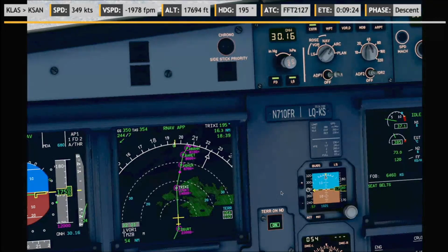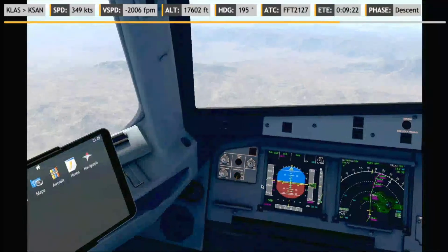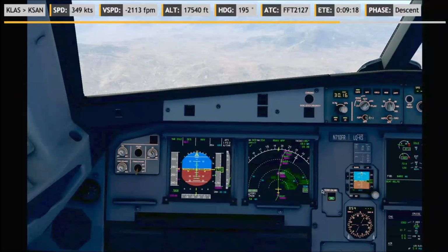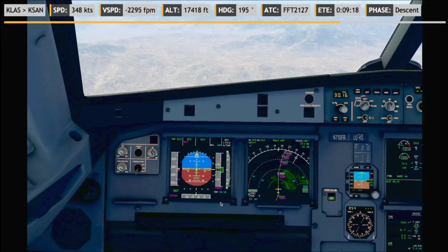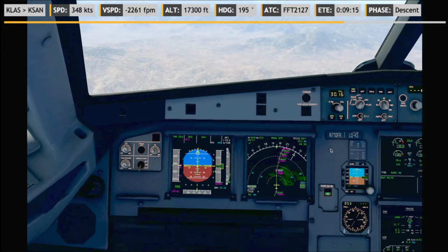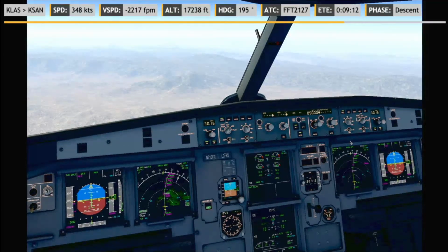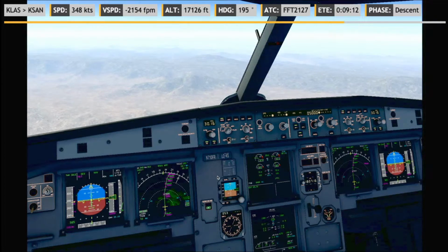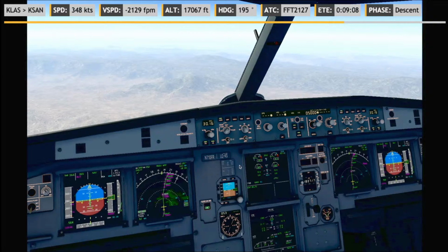Okay, this looks like it matches with the altitude that we have indicated. I don't have a ready calculation or a rule of thumb to get from inches to hectopascals, but you normally shouldn't. This should be in inches as well if you're flying here in the United States.